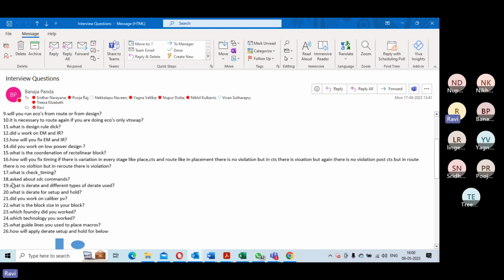So you are going to remove all the cells in the common path. Whatever derates are applied, you are going to nullify them. That is what removes the pessimism in the common path, which people call CPPR, common path pessimism removal, or CRPR.